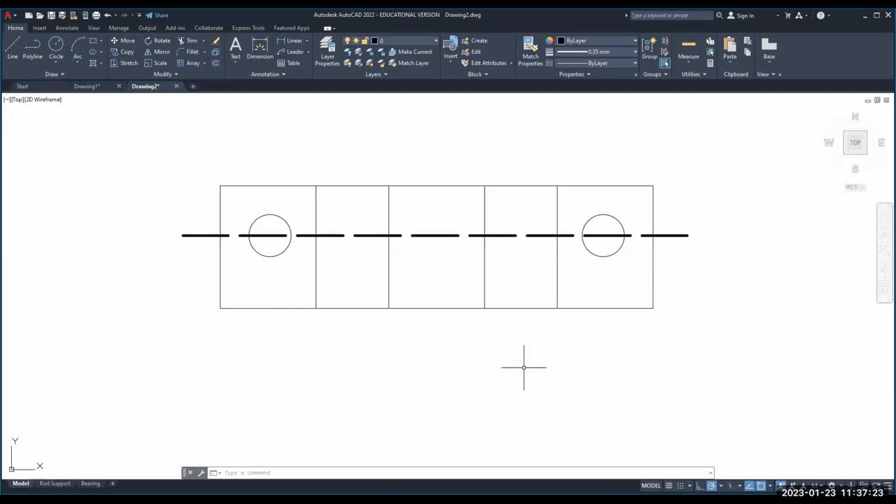All right, so here's the next part that's a little bit tricky, and that's getting these arrows on. You don't really want to use leader. That's always going to be a very small arrow. So I have to actually teach you polyline so you can make an arrow. Polylines are wide lines, and you can control the width. So you can make a line have a varying width, like an arrowhead. Instead of line, it's PL for polyline.